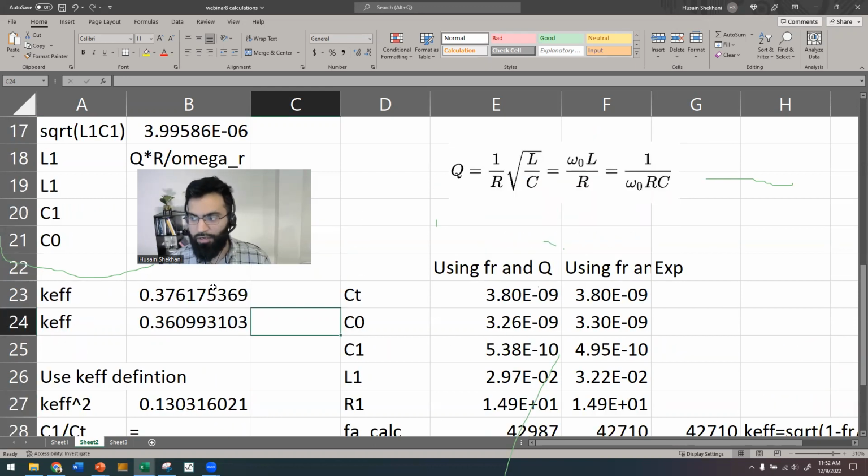But if I really wanted to dig in and understand the system better, or I had a limited measurement setup where I don't have the ability to drive at a consistent velocity or consistent displacement at resonance and anti-resonance, I may utilize this to calculate a coupling factor that I can use to explain to people, because they're more used to seeing that instead of coming up with a new measurement system and new values. And so that's the case.